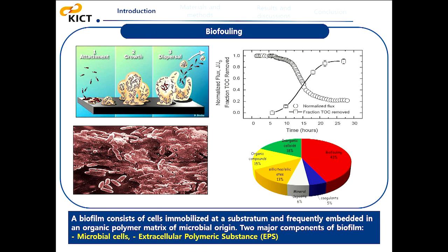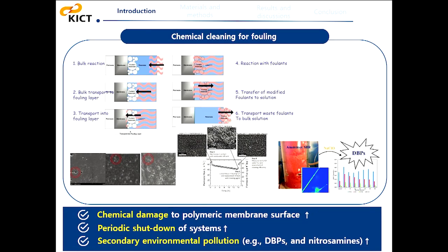proteins. Numerous strategies have been explored to mitigate biofilm formation on reverse osmosis membranes, including pre-treatment to remove biodegradable organic matter and adding chemicals to disinfect biofilm or modify the membrane surface with anti-fouling material. However, their use in combination has not yet eliminated biofilm formation on membranes. Chemical cleaning using various cleaning agents is widely used to control fouling of membrane-based water treatment processes.